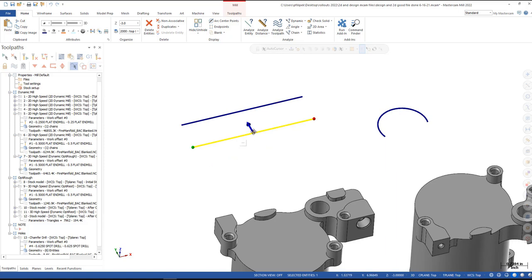I can double click on this one, hover on it, and then move it with these arrows to a specific distance. This also works on these end ones too. I can move it in a straight line that way, or if I just click on it, now I can move this line like this. One escape will get you out of everything in here. Once again, if I hover, I can move it out and extend that line out. So this works pretty good on lines and geometry like this if you want to move or copy lines around.